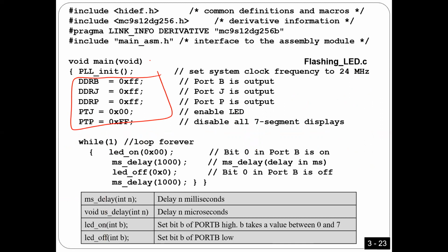Most of the time the program will be here. So we're going to do while(1). As I explained before, this is how we can create an infinite loop. Because 1 means it's like you have a condition that's always true. If you put a condition here, the microcontroller evaluates this condition. If it is true, it's going to put 1. If it is false, it's going to put 0. So you have a condition that's always true. That's why this one is going to run forever.